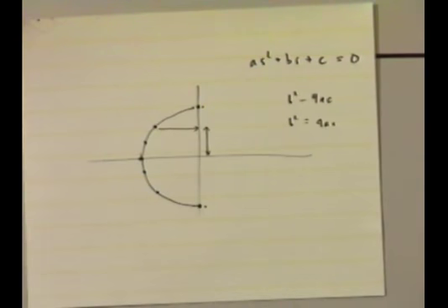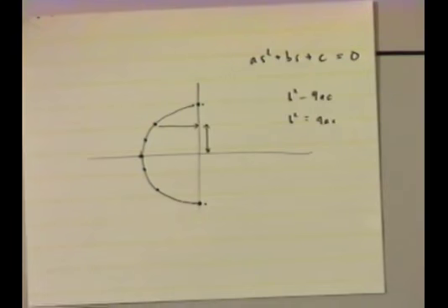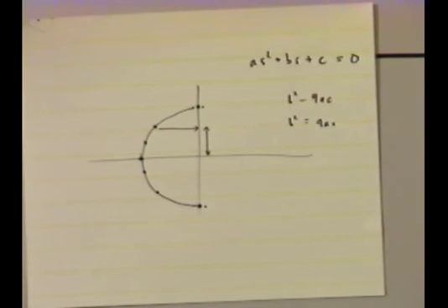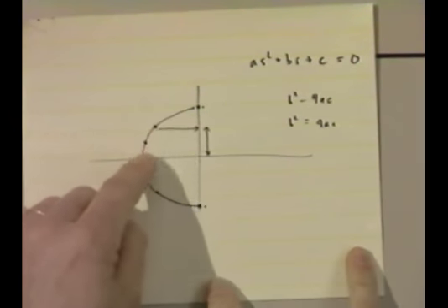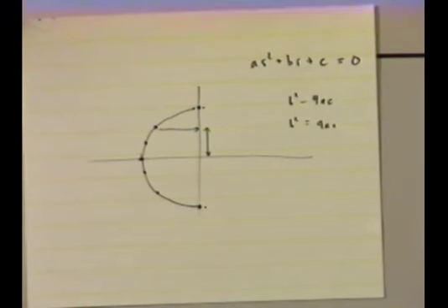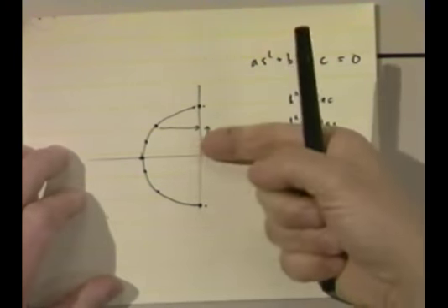So as I increase the damping, if you walk up to a car and make the shock absorber have a higher parameter, what will happen to the period when you push the car down and look at the frequency at which it goes through 0 again? It will decrease. What about the decay rate? It's also increasing, because you're moving to the left.